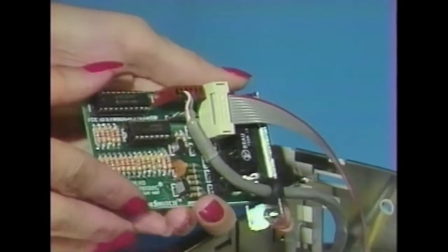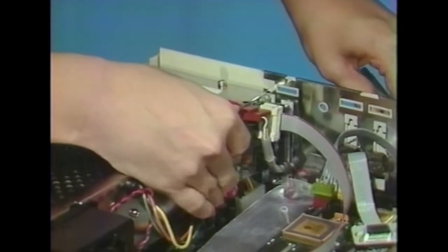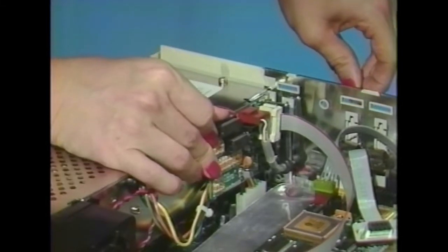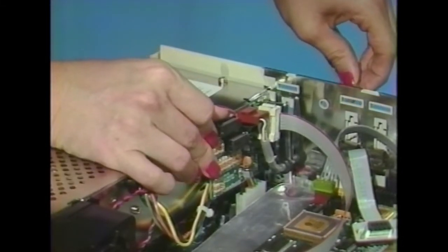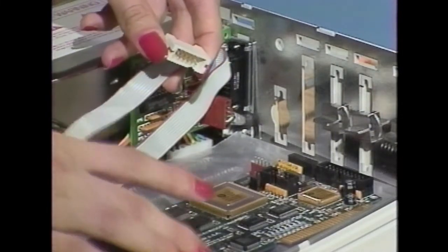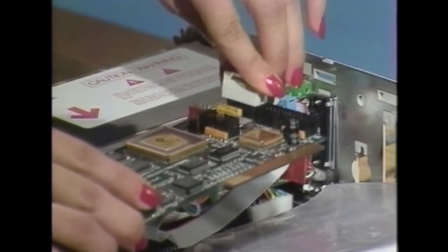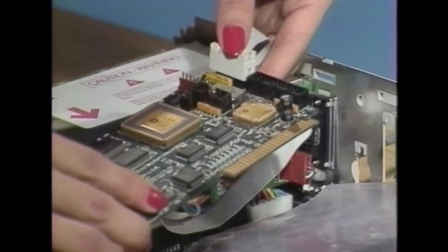Hold the color switch up to the backplane so that the screw holes of the mounting plate line up with the opening. The chip side of the board will be facing away from the power supply. Use the screws provided to secure the color switch mounting plate to the opening in the back panel. Attach the male 10-pin connector leading from the color switch to the female 10-pin connector on the transporter.